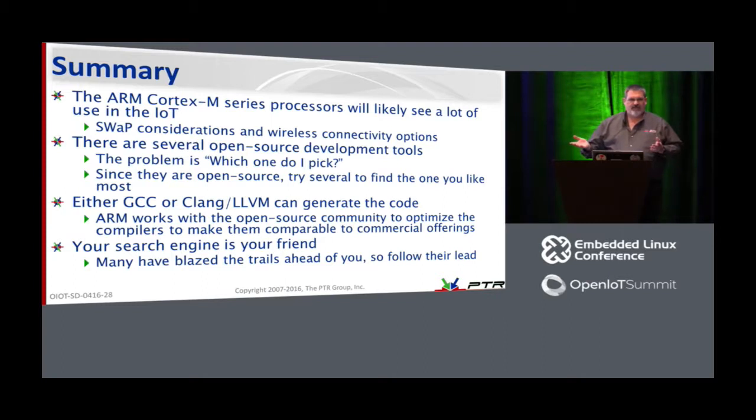There are fab houses, silicon fabs out there, surely, but there are board houses that'll spin a copy of the board for us, and they'll do one panel. So we don't need to spend thousands of dollars to do a run of a printed circuit board. We can get the Gerbers off the open source community, put them into our CAD, spin a new copy of the board, send it out to one of these board fab houses, and they'll turn it around within a week. And we'll have 5 boards, whatever happened to fit on the panel, and we'll then have the opportunity to start stuffing it and getting it ready to actually do some testing. So we have a lot of options available to us.